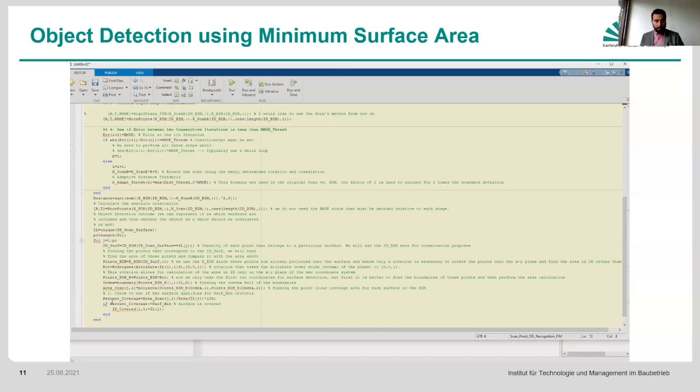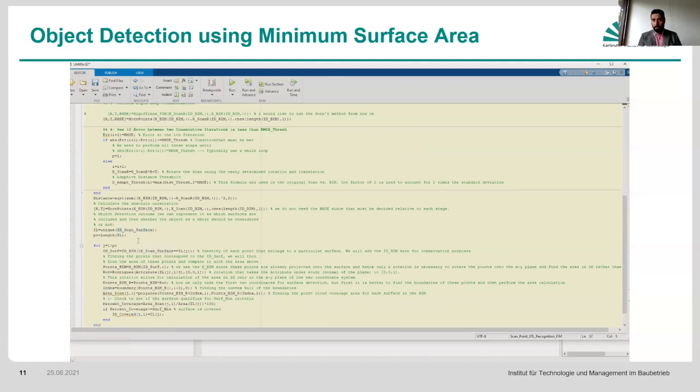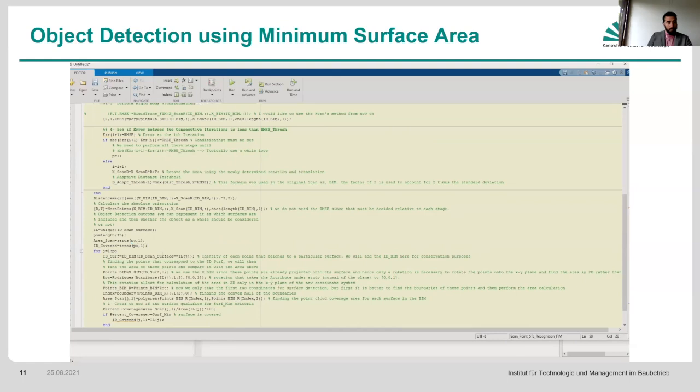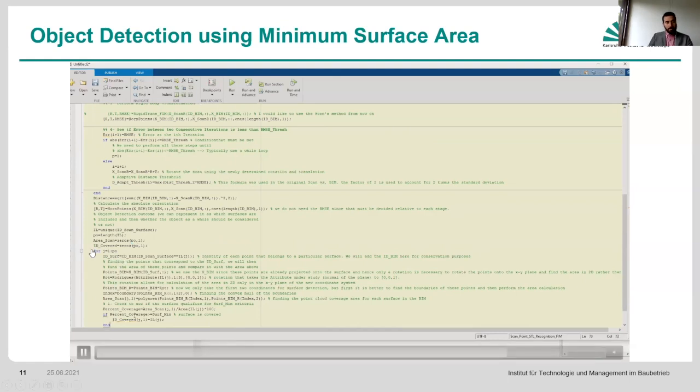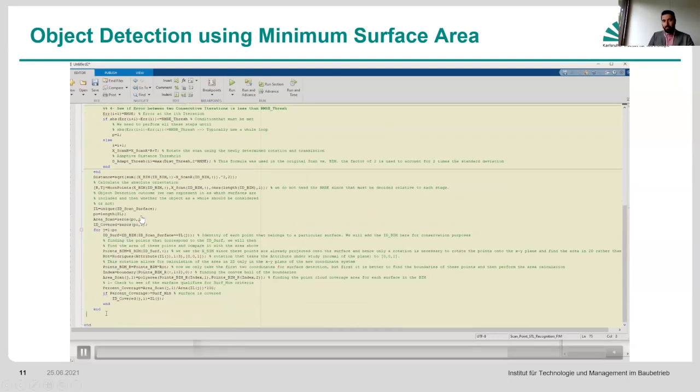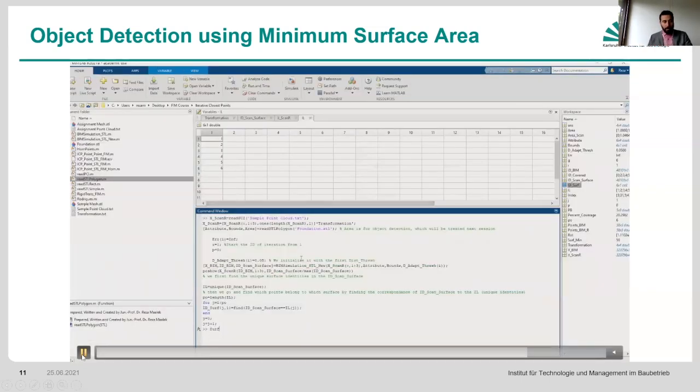I've said, okay, we not only have it as an ID, but we also have it as a function of the surface that it actually represents, or equal to 1. So we just initialize the ID underline cover, and this is just good practice to do, to make sure that you have enough points there. So let's just copy what we had there with a surf underline min of, let's say, 50.